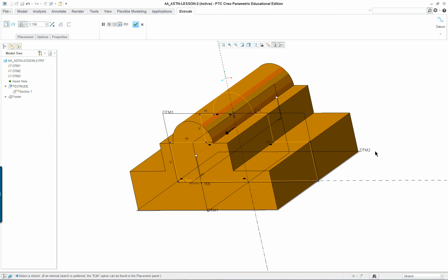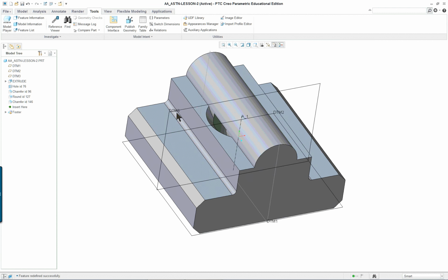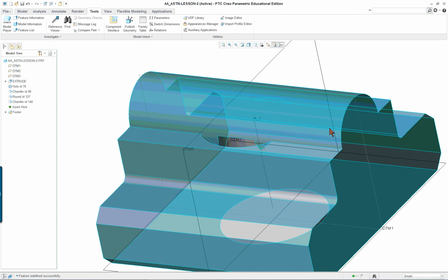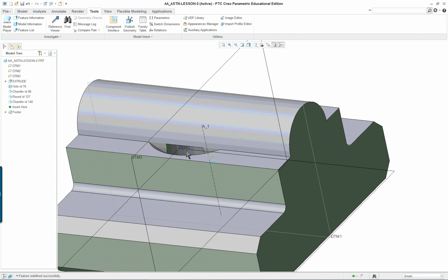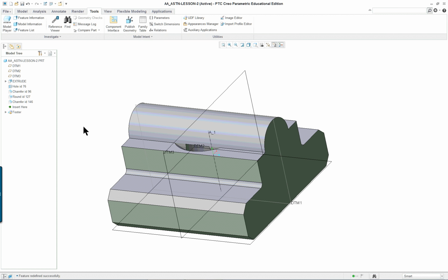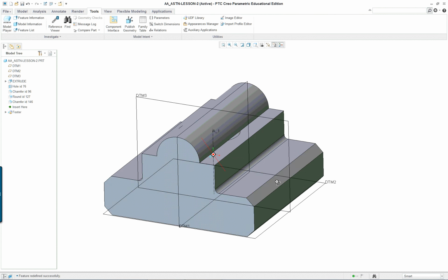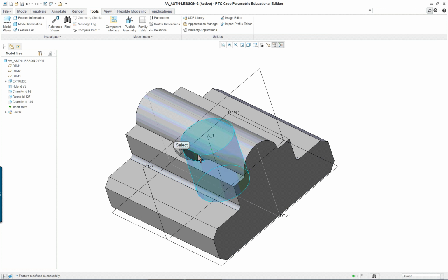Now what happens here? All right, now here's my extrude, but what happened? Kind of funny. I put a protrusion on the top, and where the hole is, now we got a problem, right? Because I covered up the hole with that particular feature. So I went back and I altered the parent, and it then kind of screwed up where the child is of that particular parent feature.